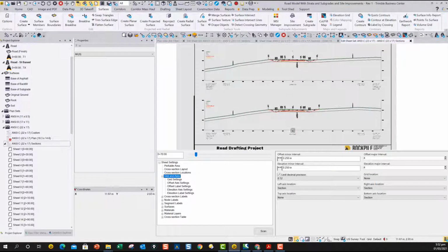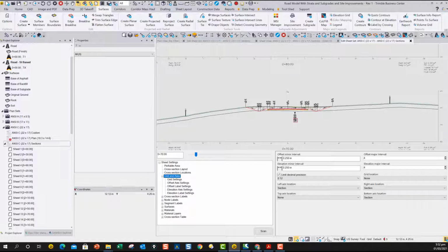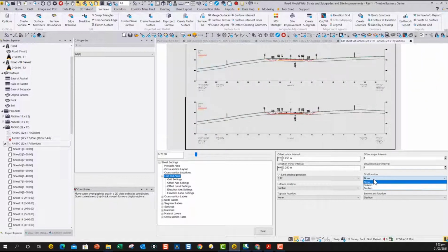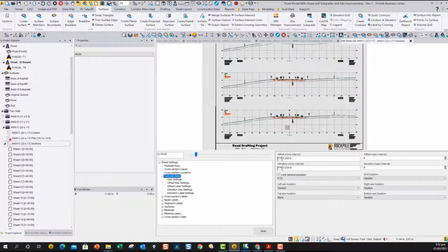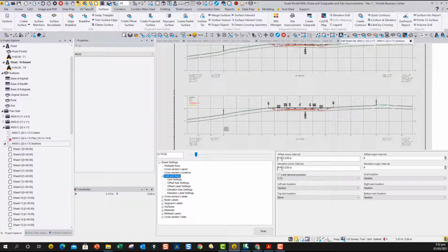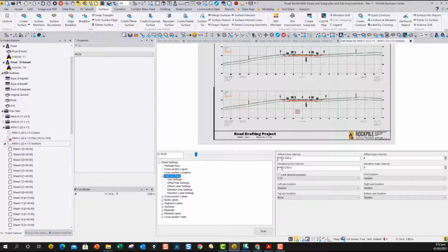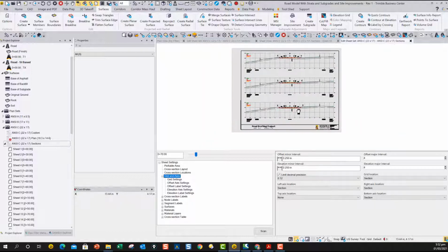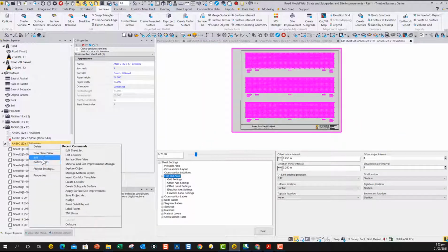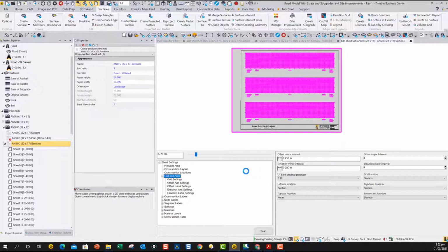The only thing I'm missing there is a centerline axis here, if that's the case. I prefer to put the section lines on, and then I would create the grids, and then I could just turn off the minor grids and maybe make my major grids much bigger or something like that to get the look that you want for the centerline. But anyway, you can do all those changes in here if you need to. And now I'm ready for this. I can then go to build sheets and build all my cross-section sheets from this.